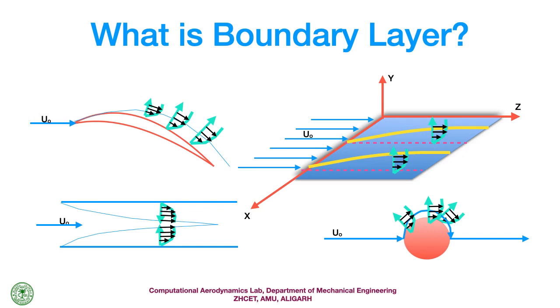Now, what is the effect of this boundary layer? As the video shows, this viscosity influences the shear stress on the surface, and this shear stress or skin friction in turn integrates to cause the drag force, a force on the body. For an engineer, this drag force is an important concept.